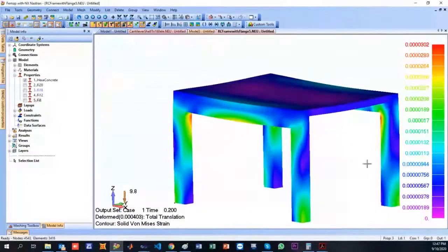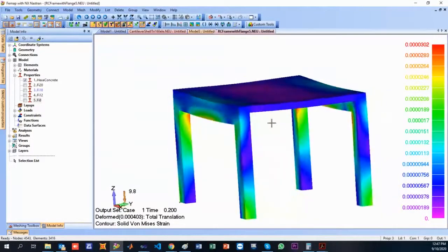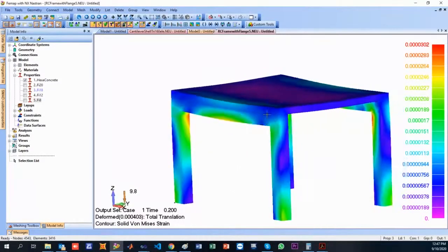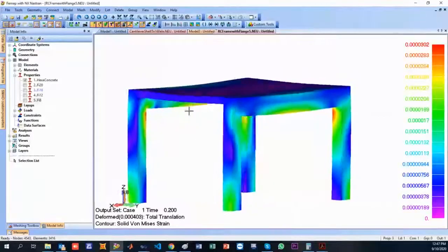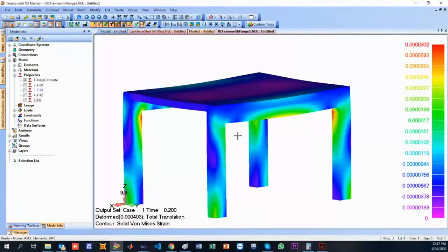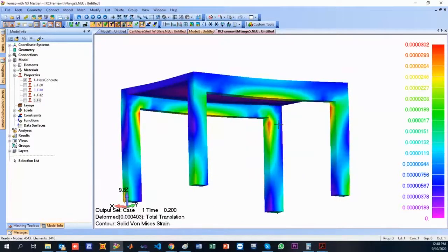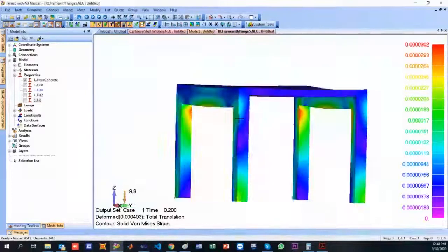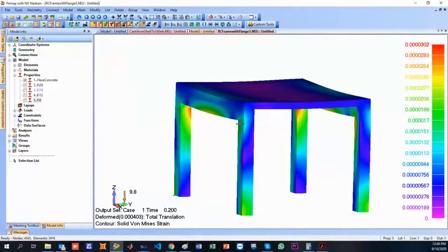4.8 meter span, 3.6 longer span, bending of the beam, even though I don't have, in this case, a drop beam along this direction, right? So due to the fact that this is almost 5 meter span, it's affected more, and the deformation that is developed looks like this. Also here in the corner, here, there, and there, I see the development of deformation due to the asymmetric bending.